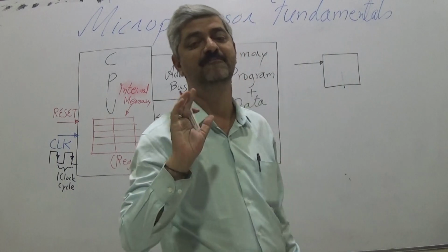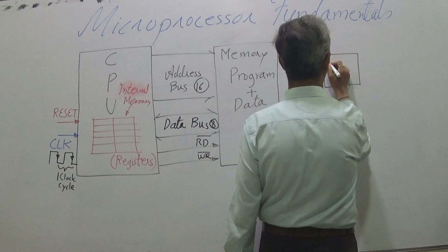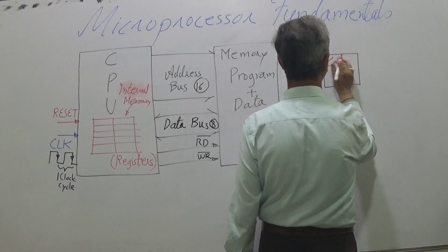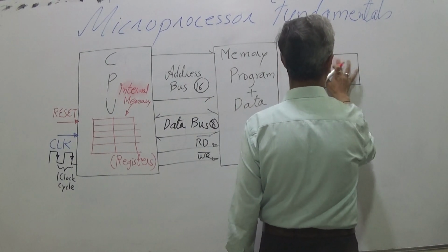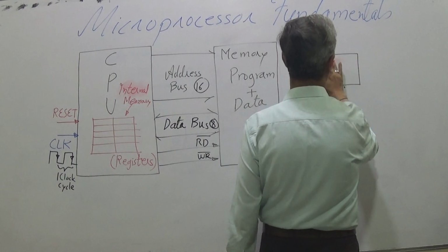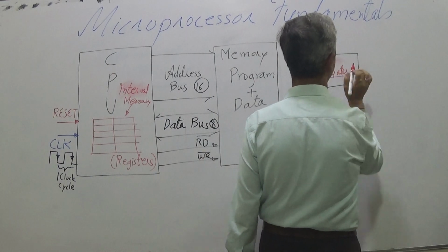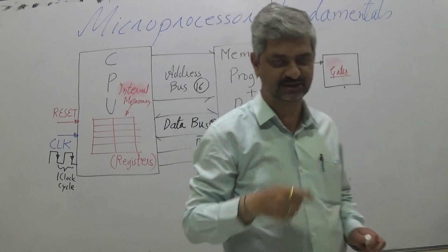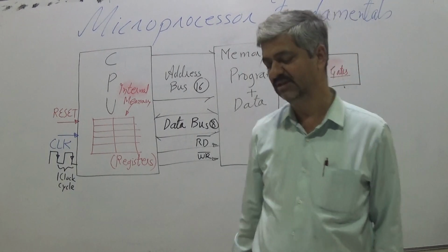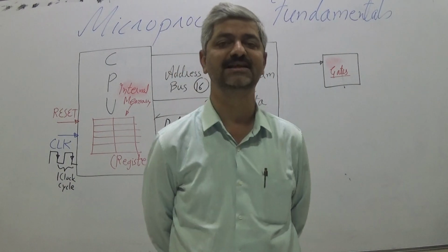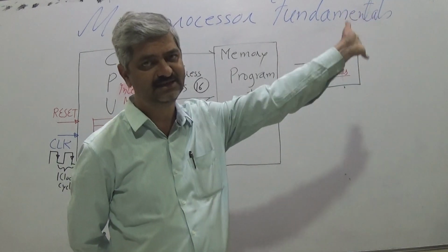What is a digital circuit? A digital circuit is comprised of various logic gates. A circuit which does not have feedback is called a combinational circuit. A circuit which has feedback is called a sequential circuit. A flip-flop is a sequential circuit, so some arrangement of gates is there inside.